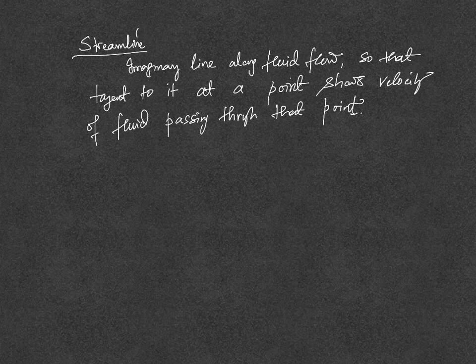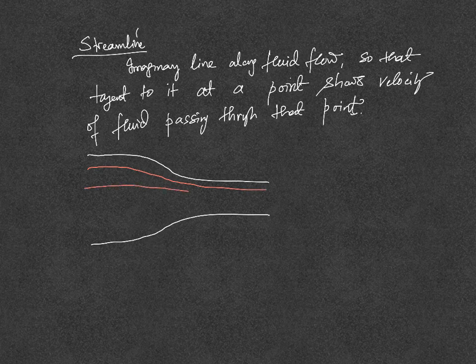See, don't confuse streamline with locus, right? It's not the same. But for steady flow, it is the same as the locus of a fluid particle. In a steady flow, the streamlines are fixed. Say this bent pipe, I'll tell you. For this bent pipe, these red lines are the streamlines I'll draw. And they are given some directions also, else you never know which way the liquid flows.